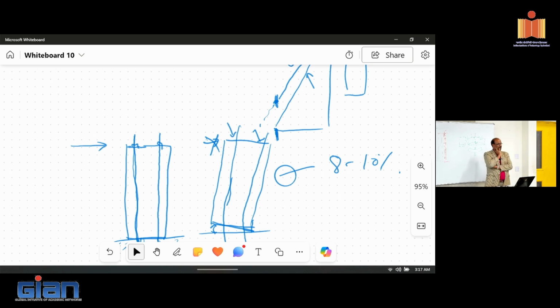From the earthquake point of view, when we do elastic analysis, we assume 5% damping, so we estimate our demand. But for a structure to survive an earthquake, you are saying we may need about 25 to 30% damping, right? That predominantly comes from cracking. Now here, you keep the prestressing strand elastic. How does that achieve it? No, what I said was that the 25 to 35% damping was not invented as a requirement.